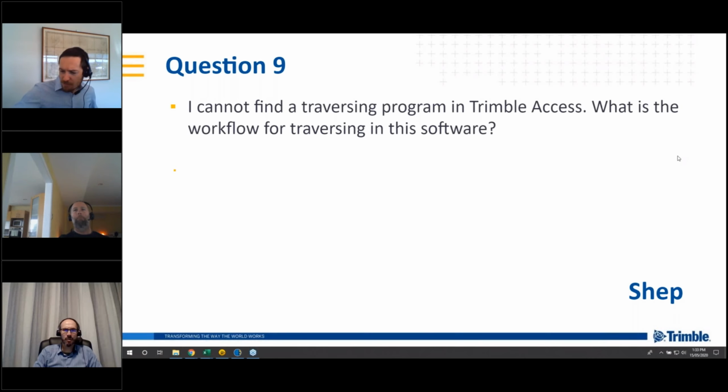Yeah, there is actually. I think with station setup and with measure rounds, there is actually a traversing mode. What that does is it makes some assumptions, so you'll put your foresight and make that the backsight target record for the next setup and all that. So it helps automate it a bit, so you've got the correct target height and that type of thing.